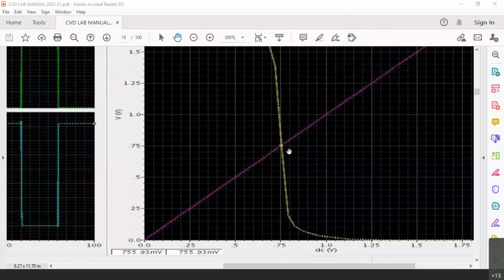Increase the P size of the thing. Okay, like increase the mobility. PMOS, increase what? Vanilla is correct. You have to increase the P size. In the PMOS, increase which dimension? Like length or width, sir, or what? Yeah. Whether length or width.